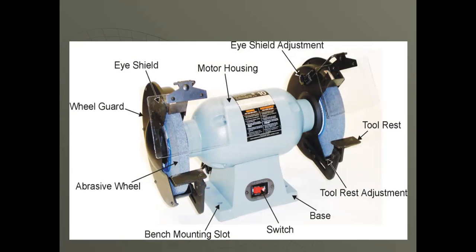Are they good? Yes, they're good. Do they get broken and damaged, and do they often get removed from these tools? Yes. So that's why I always implement face shields. These wheel guards, they get mucked up pretty quick, and they just aren't very good as far as providing adequate safety. So I think face shields are best. So that's what we wear in the shop.